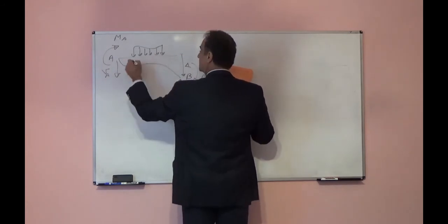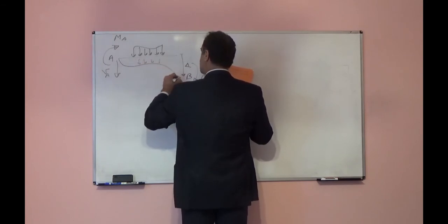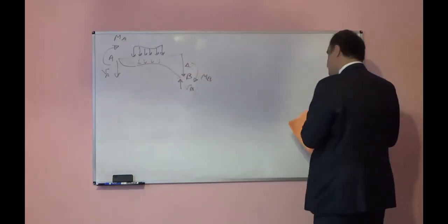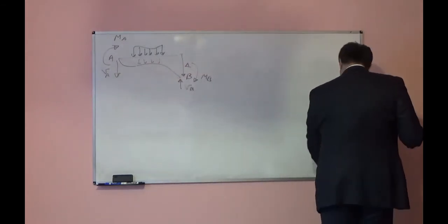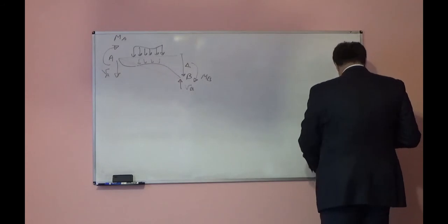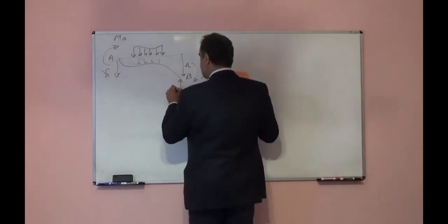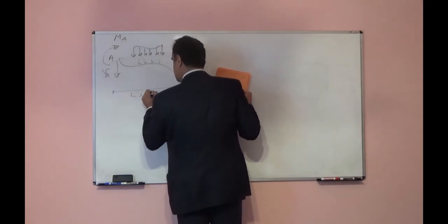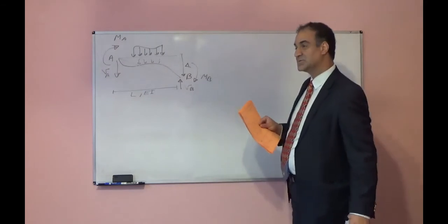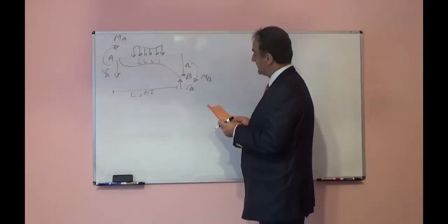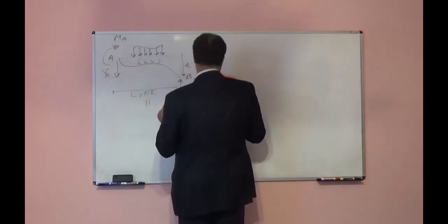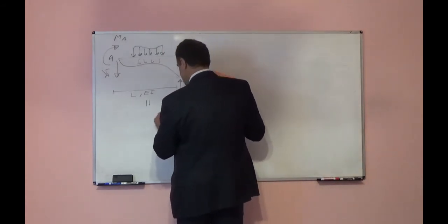So the load will transfer here after deformation, and you remember initially it was a straight line, but then it will deform something like that. Using superposition, if the member length is L and EI is constant, we can divide this into different systems, 4 different structures.